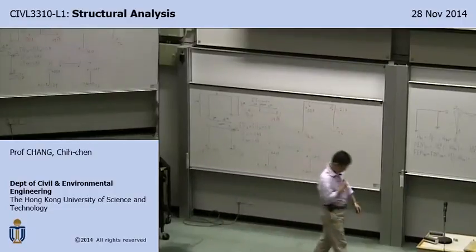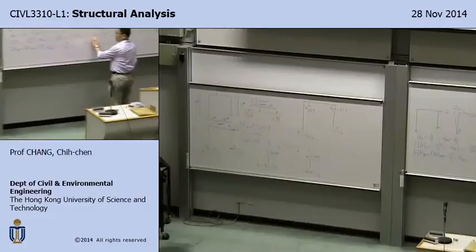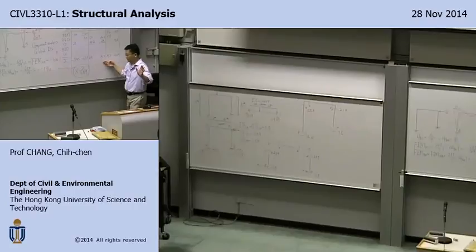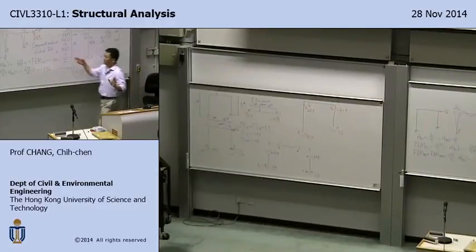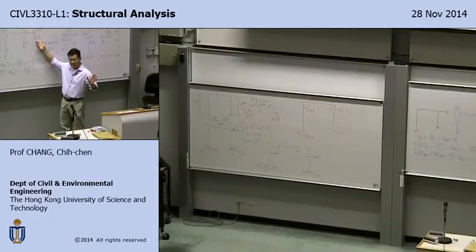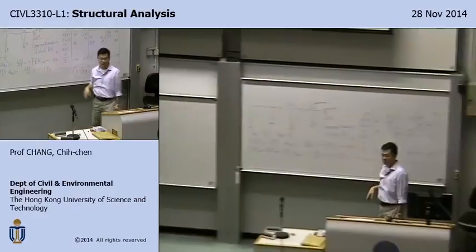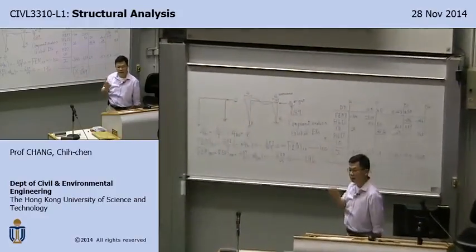So what happened if I assume this to be minus 200? Can you guess what happened if this is minus 200? Hello? Anybody know? If I assume this to be minus 200, what happened? Then everything here will be double, right? This value will be double. So the scale factor will be changed. So this is double, and scale factor is like half. So they multiply, go back exactly the same. So that just shows you that it doesn't really matter how you assume delta.